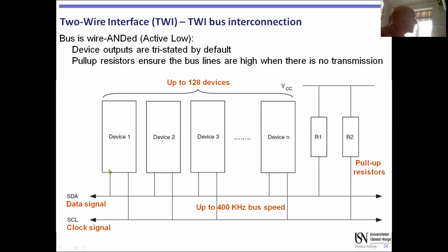You could use this so that 1 temperature sensor is connected to multiple Atmels, because normally you would think, oh, well, I might have 1 Atmel with 3 temperature sensors, but you might also have 1 temperature sensor with 3 Atmels with this, if you're careful how you configure it. So this could be a mixture of Atmels, other microcontrollers. It could be some Atmels and some other manufacturers' devices, and some temperature sensors and all kinds of things all